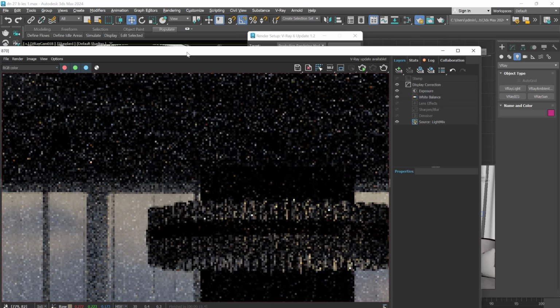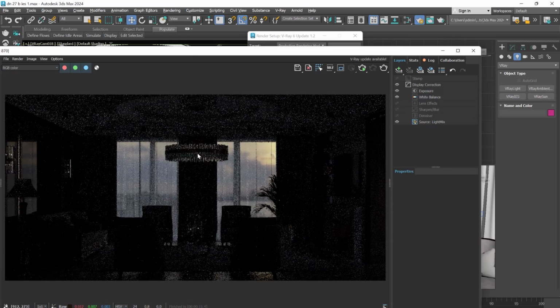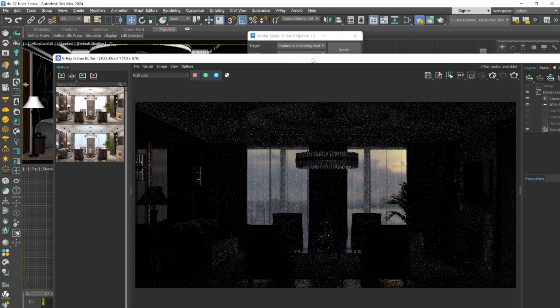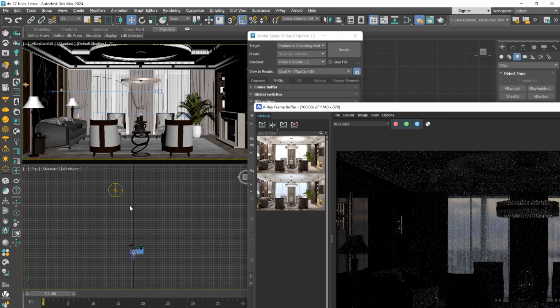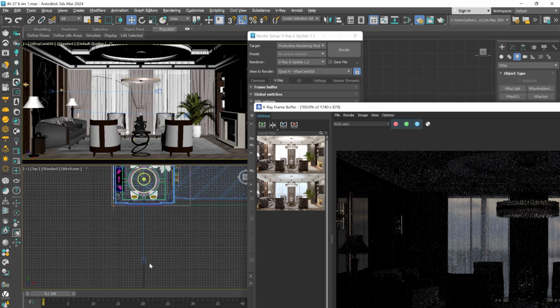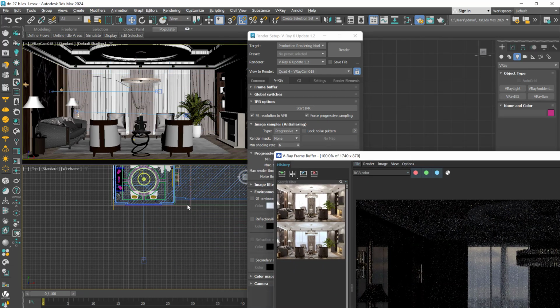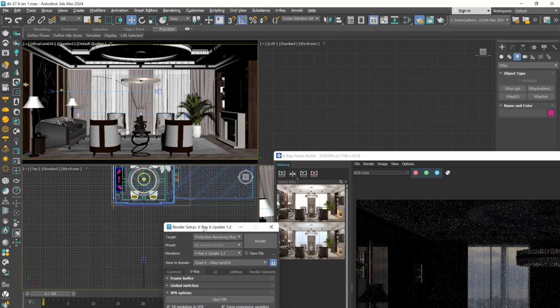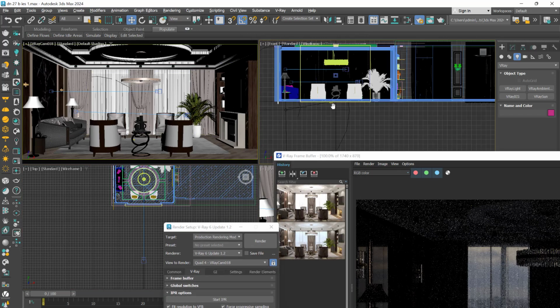Let's pick, for example, this first one. And you can see here our previous scene. I've turned off all the lights except for the dome light, our HDRI, and I've also disabled the sun as well. We will use this camera view for the start. We will create an IES light and we will see how it acts in our render. Such files are usually provided by the manufacturer, and the information is tested in experiments and it's extremely accurate.